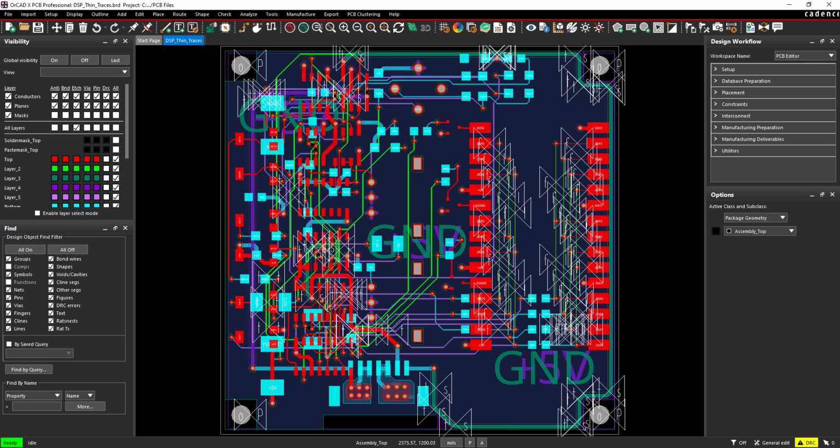With the constraints assigned, we can now use the software to identify potential manufacturing issues. If the DRC button in the bottom right corner of the screen is red, the DRC cache is out of date. Select the button and click Update. DRC markers have appeared throughout the board. Hover your cursor over one of the errors for additional information.